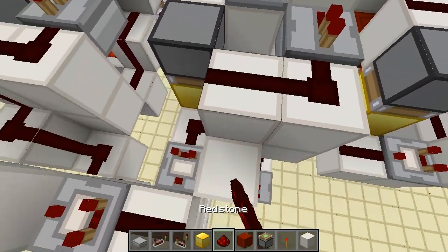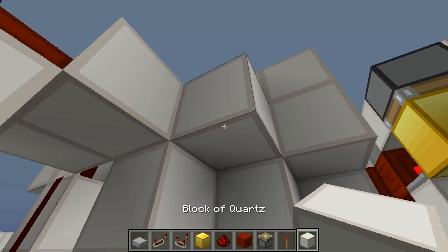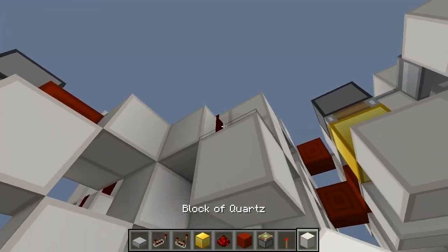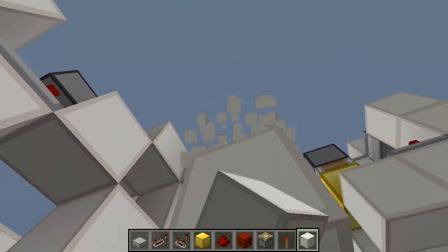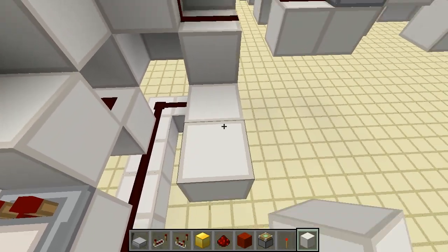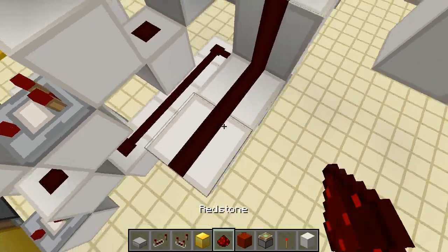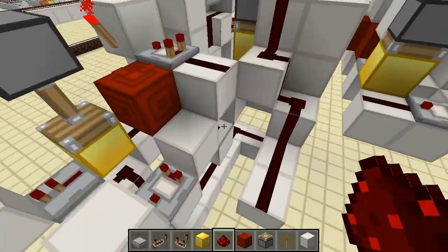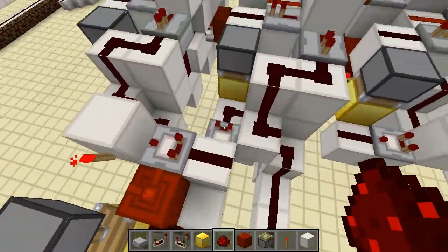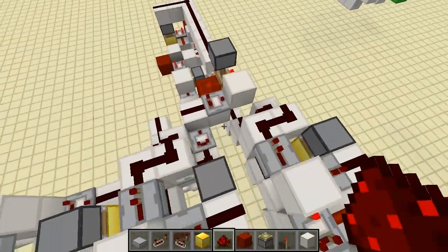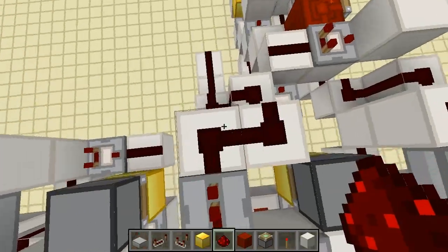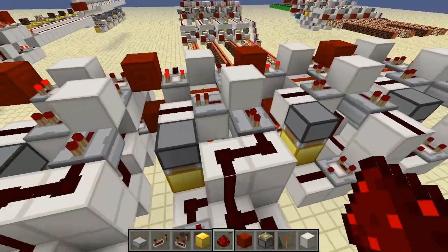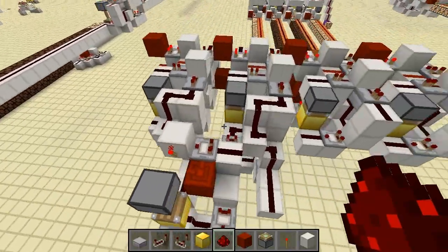So yes, if we bring the carry out line from this next digit down, the same as we did for that digit, it comes down here and out, and as you can see, the carry out from the previous digit is pushed onto the next digit, which is exactly what we wanted. Well, actually, technically, this is already the carry out from this digit. We're setting it to 1 because the logic is stepped across this way.